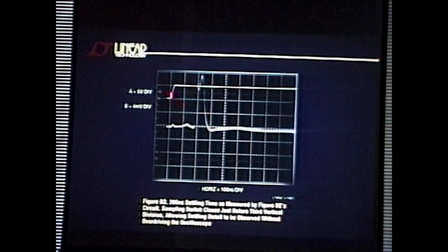The guy on top is the input pulse. That's telling the DAC and the one-shot to go to work. So during this interval here, the waveform is slewing 10 volts. It's going right through the roof, and you can see the bridge rejects just about everything. There's a few millivolts of stuff in here leaking through as the bridge is moving volts at speed.